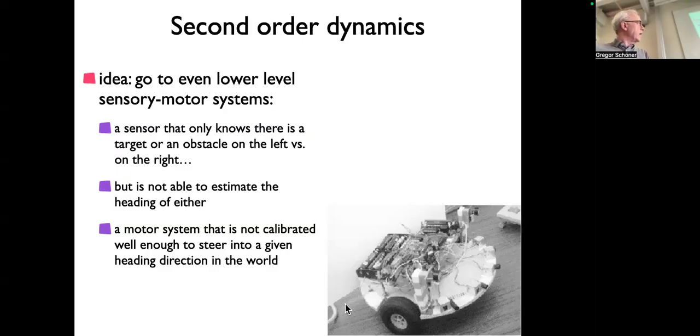We also had non-calibrated motors. That is, these motors were driven by little servo motors in which we actually disconnected the servo. We took toy plane models that control the flaps, and we just cut off the sensor circuit, literally by cutting off the cable. Therefore, they're motors that just take a voltage, and there will be a certain turning rate coming from their voltage, but it will not be calibrated.